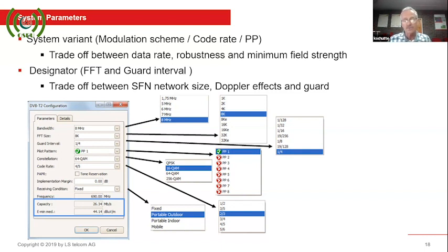So if you've got transmitters over that, and you've got a receive point, then if the difference in distance from the one to the other is more than 159 kilometers, you will start experiencing interference. But in our environment, you should be more or less interference-free if you've got a 1/4 guard interval.